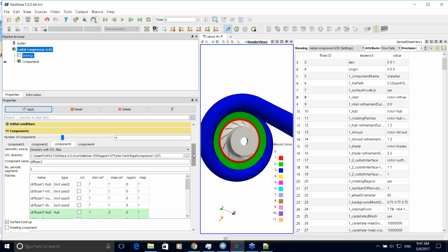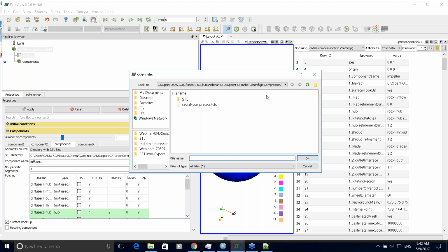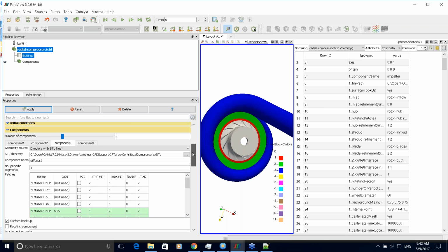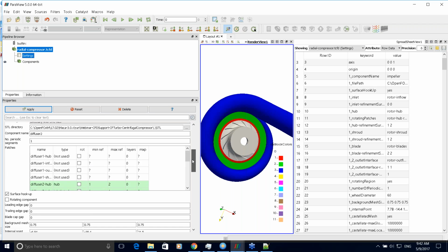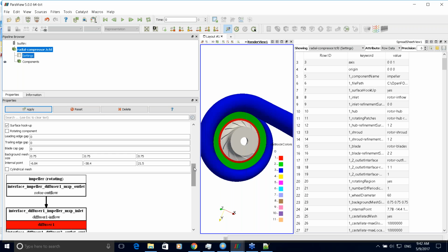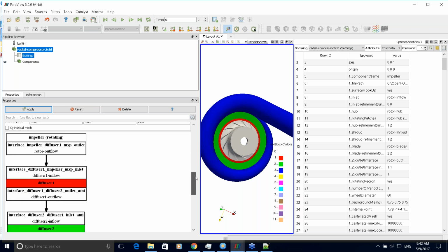In general, this software also provides the usage of an external mesh. So you can distinguish here. So external OpenFOAM mesh, it means you can use almost any external mesh which is converted to OpenFOAM and use it for the simulation. Other parameters are related to the SnappyHexMesh, which defines the maximum size of the cell inside the geometry and so on.